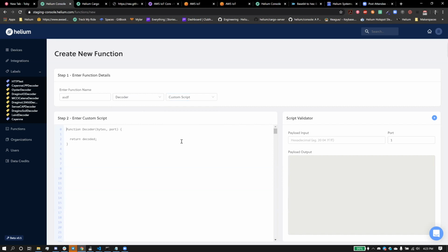And this is just in JavaScript, and it allows me to have my input and then what port we're going to operate. And what I mean by port is sometimes with sensors, I will run GPS on a particular port number. I will run maybe a temperature sensor on a particular port number. And then I can stagger those across time, and so I'm not necessarily just having a huge payload that's being uploaded all at once. I can say, okay, here's temperature, here's temperature, here's temperature, here's GPS.